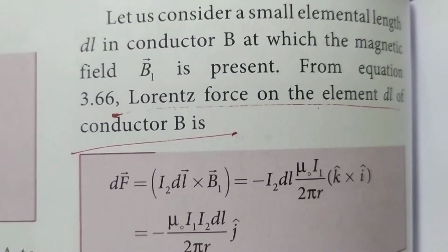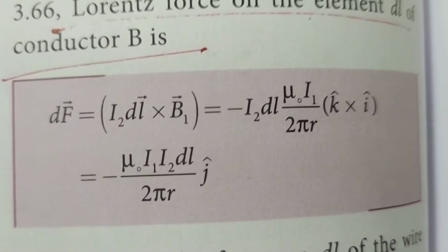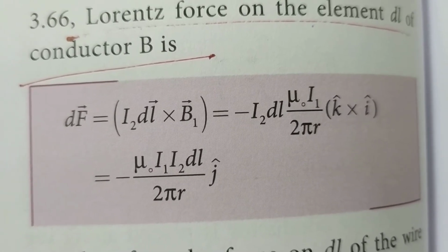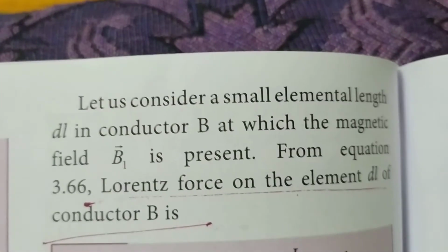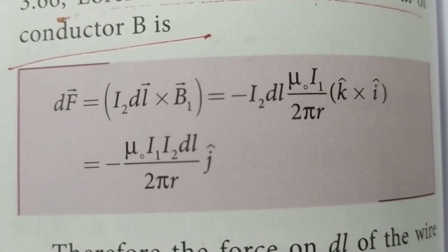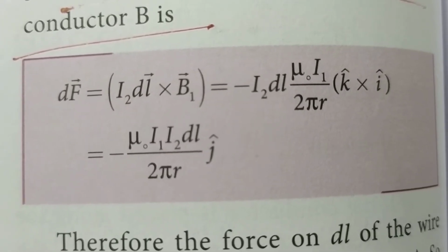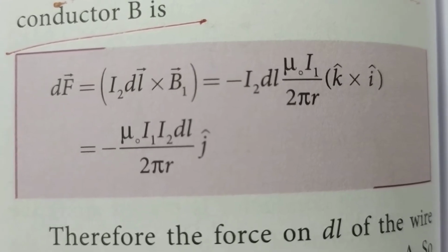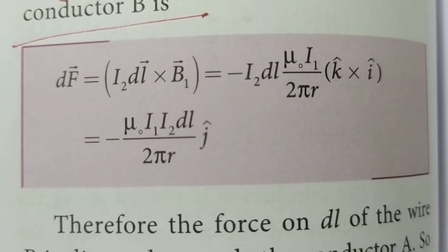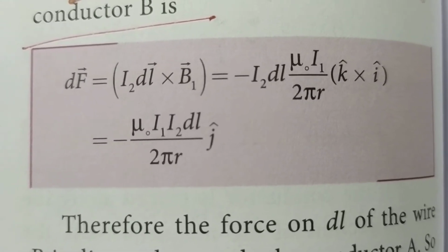Next we are going to see the Lorentz force, and you know the Lorentz force equation. dF vector is, for a small element dl at the next conductor B. First we have seen the current flowing through the conductor A. Now consider a small elemental length dl in conductor B, so dF vector is equal to I2 dl vector cross B1 vector. Here I2 is the current flowing through the second conductor. Instead of B1 you can substitute mu naught I1 by 2 pi r, which is the magnetic induction due to the straight conductor, and